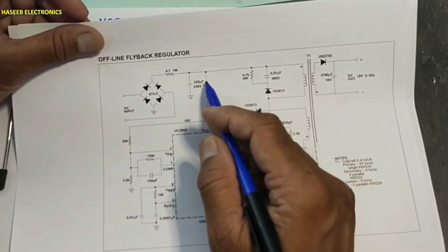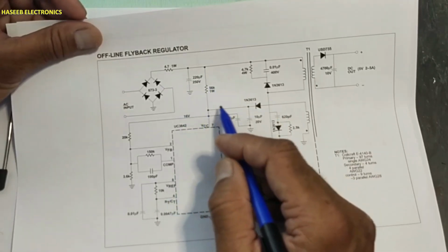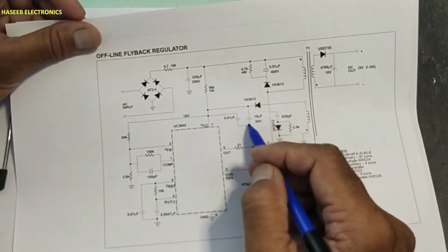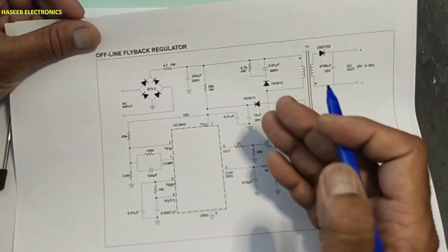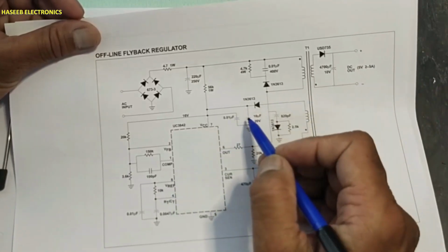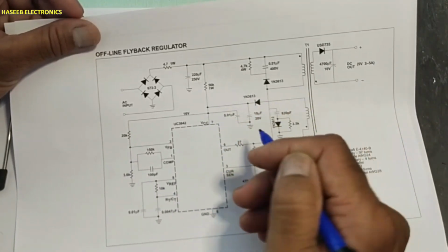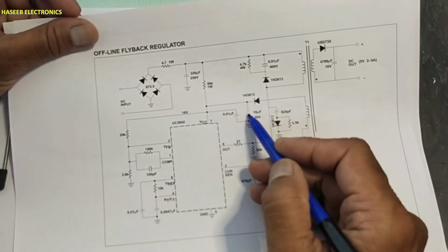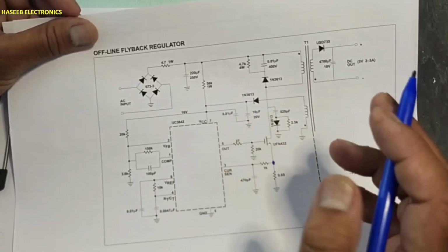That means this source is providing just only 300 microampere for charging. And now if there is no other source that can provide the required current, the voltage level at this capacitor will start to decrease, because now this is working as a battery, so it will start to discharge.